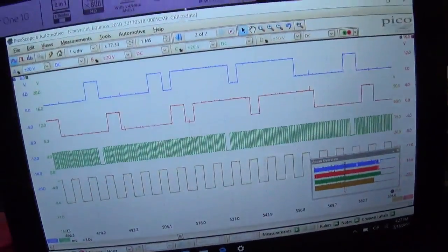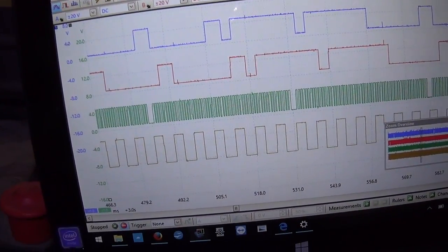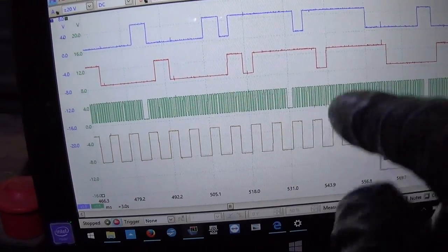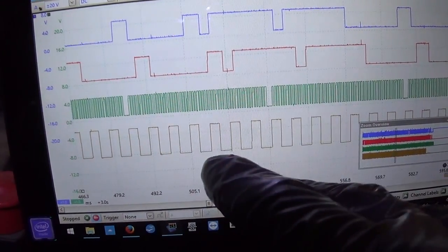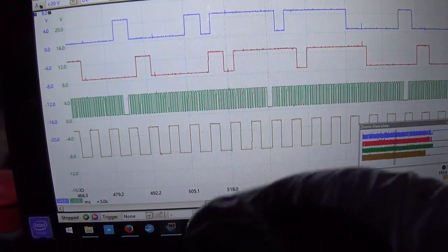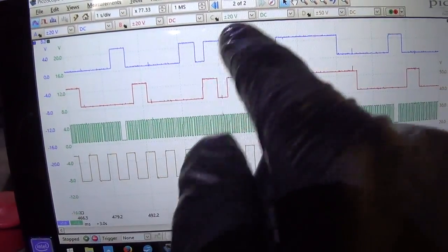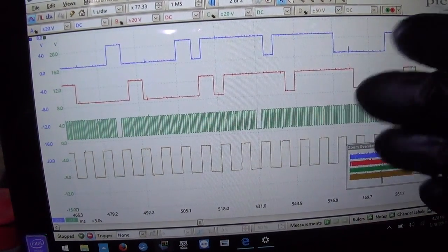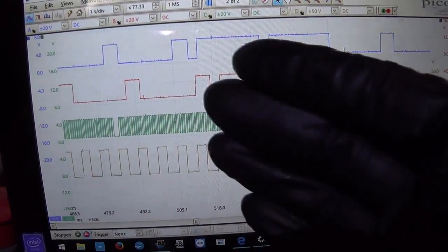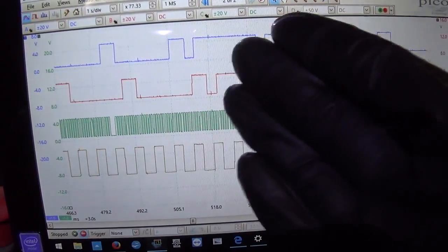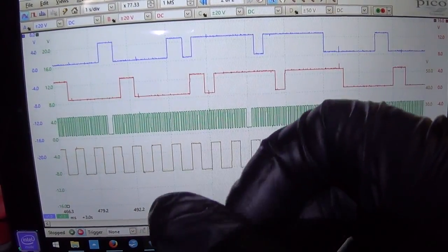So this is interesting. So intake, exhaust, crankshaft position sensor, and the duty cycle control on the positive side on that exhaust solenoid. Now, as we saw in the scanner, it was about 50% duty cycle, and that's exactly what we see on our scope. So that matches. Now, cam and crank correlation. Is this good? Is this bad? I don't have a known good waveform at idle at the moment, so we're just gathering data and seeing if we can change these based on our command from our scanner or from the engine computer.